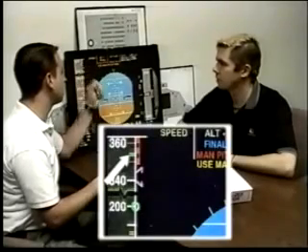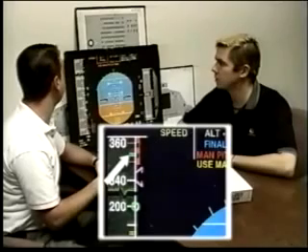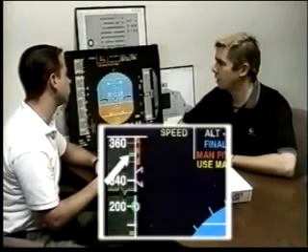Okay, what occurs at Vmax? Well, as we accelerate past Vmax, we're going to get a continuous repetitive chime, and we'll also get an ECAM with that. If you accelerate through Vmax, we have these double green tick marks. What is that called? That's called high-speed protection. And what occurs at that? That occurs at 6 knots above VMO or 0.01 above MMO, and we'll have an autopilot disconnect, the airplane will roll wings level, and uncommanded pitch up.